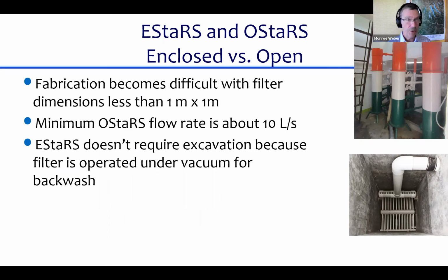They don't require as much excavation. They don't need to be so tall. An open stacked rapid sand filter ends up being close to 5 meters tall, or 5 meters deep. It's this really deep tank. The enclosed filter doesn't have to be so deep.